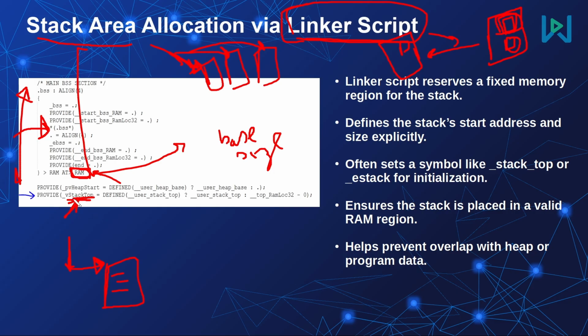So this value will go to the CPU stack pointer, and then once the CPU starts executing our program, every time we have a push operation, the stack pointer will decrement by the size of the pushed data element. This is of course if our stack pointer is decreasing.